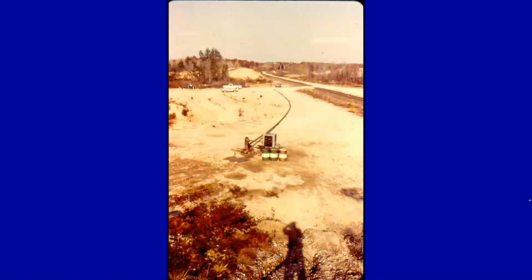All right, conducting a pumping test. You have to be able to take the water being pumped and discharge it far enough away that in fact it is not going to be able to come back and provide recharge, overinflating the potential capacity of the well.